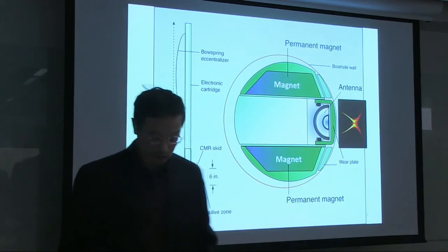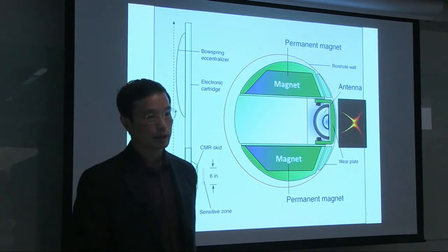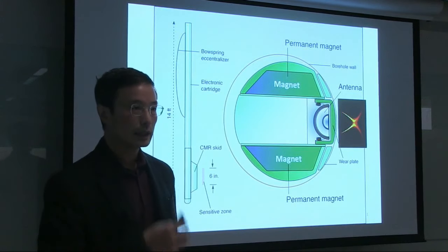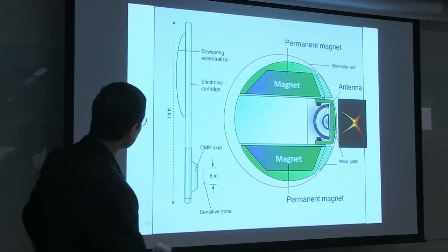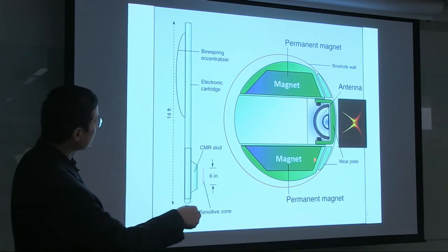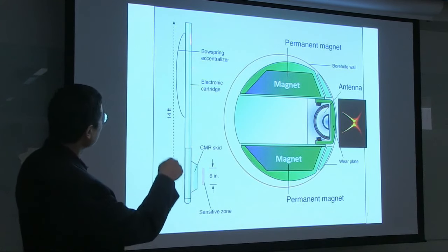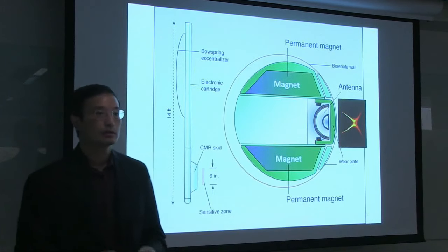Then the sensitivity spot is in the formation. So this is how you can do NMR or MRI in an inside-out geometry, allowing you to probe the formation. And overall, of course, this is only talking about the NMR sensor, and that would be here, and then you certainly have a lot of electronics that you have to package into the logging system.